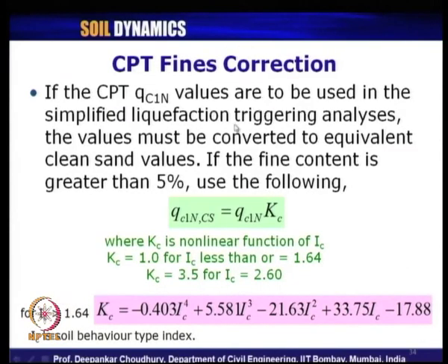So, CPT fines correction is also required for liquefaction analysis. Similar to our SPT fines correction, this is also required only for the liquefaction analysis, not for other study or other design process, whereas the overburden correction factor is required for all other design processes also. So, CPT QC1N, whatever corrected value of cone penetration test value we got after applying the overburden correction factor, needs to be corrected for simplified liquefaction analysis in terms of equivalent clean sand.